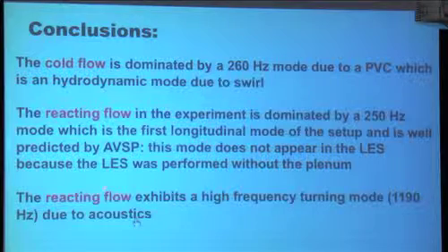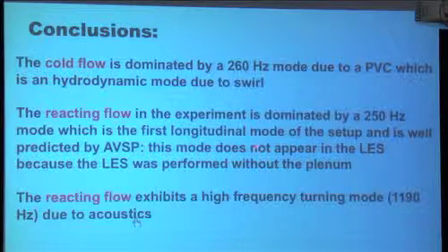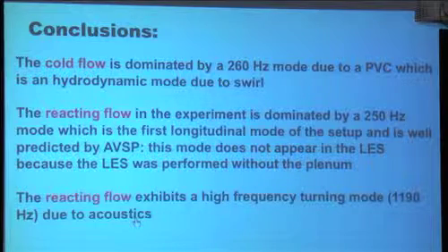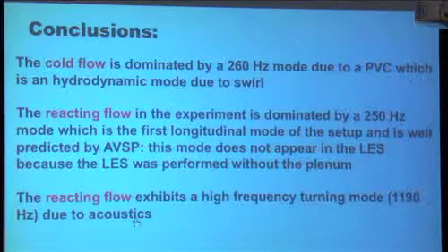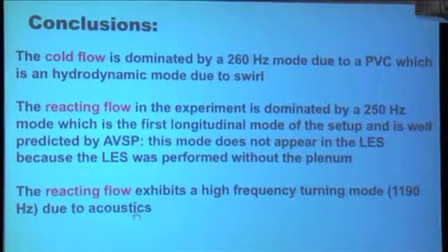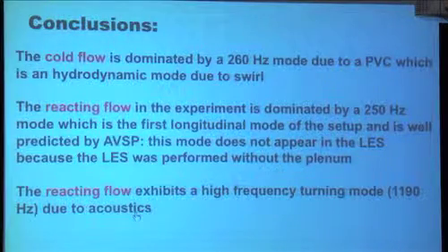And in addition to that, we can say that it's controlled by the plenum, which is also interesting because in Karlsruhe, when they designed the plenum, they used any plenum. They just put a plenum. But in the end, everything was controlled by the plenum. So it's again the same problem. They thought that the chamber was the problem, but if you fit it to another plenum, what you really get in that case is something which is controlled by the plenum. And it really, again, says that if you're looking at thermoacoustics, you have to worry about what you put at the inlet and the outlet of the chamber.